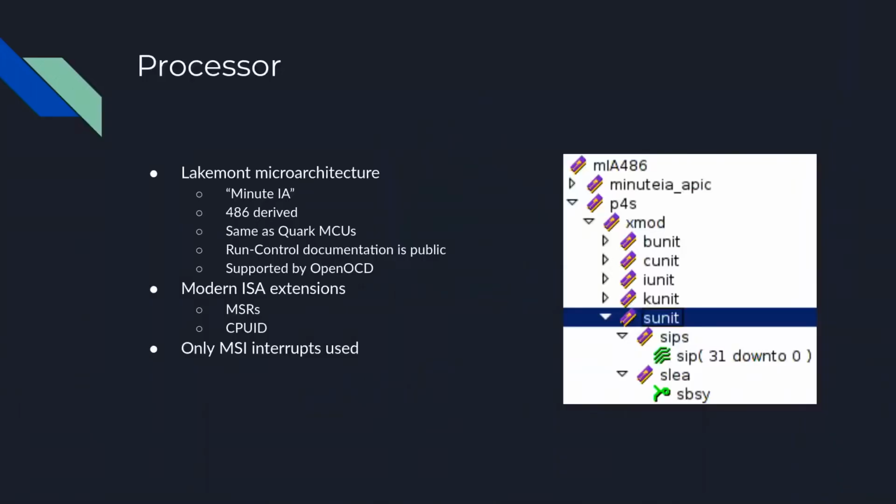So it's an IP block, but there's some files out there, which is where this screenshot is from, that are used by a built-in logic analyzer Intel has on the chipset, and you can select different signals on the chip to watch. Which is a really great source of information on how the IP blocks are laid out and what signals are in there, because you basically get a tree view of the IP blocks on the chip and some of their signals. They don't use the legacy interrupt system.